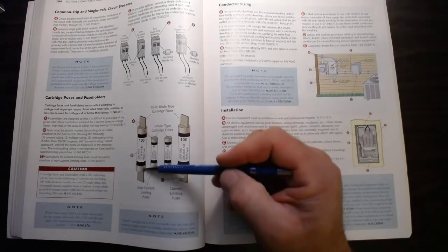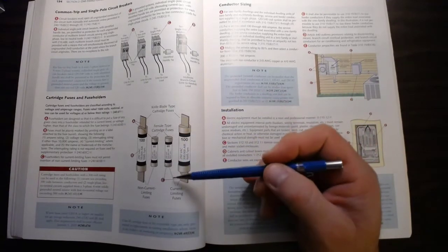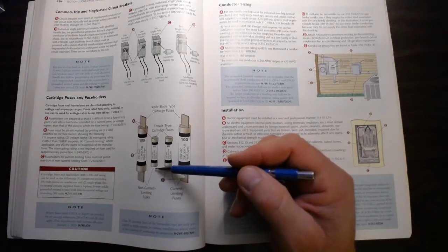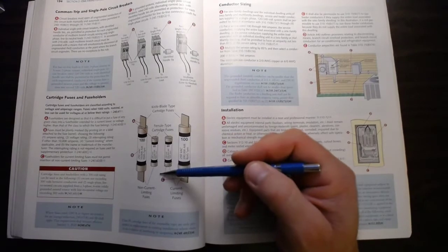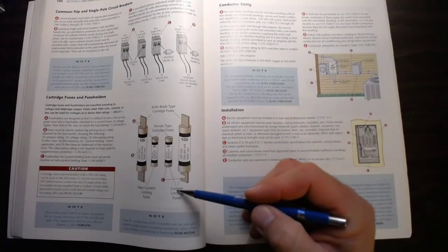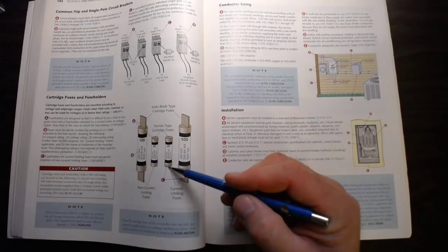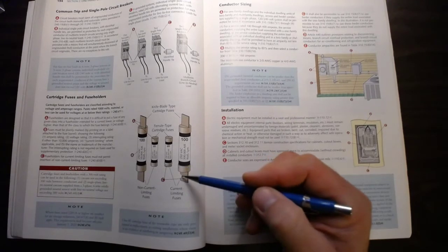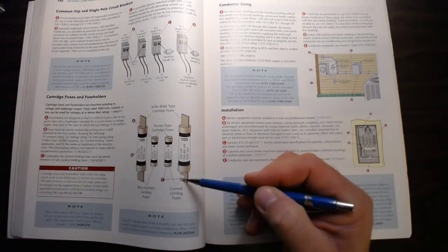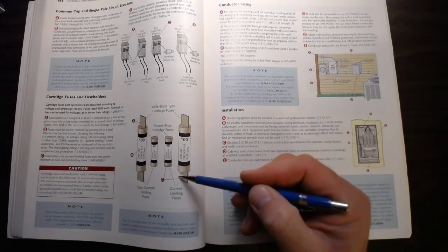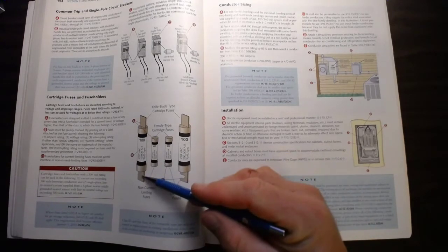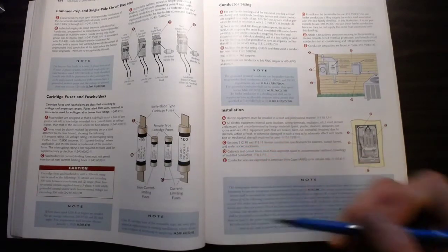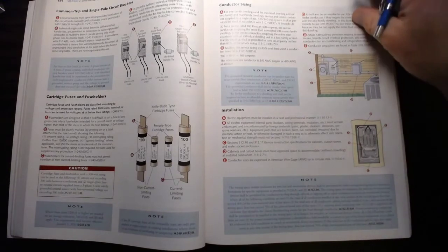So the fuses correlate with that size. So if you need to go from a 30 to a 60, then you need to actually change the whole fusible disconnect enclosure and then get the new fuses to go in. For current limiting, we see a rejection style construction to it. It has this lip at the bottom, and over here we have a rejection style blade where there would be a bar across here that you can't put this fuse into this type of fuse holder. So you have to look at what type of fuse you're using in order to get the right one.